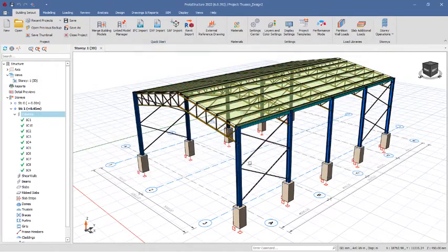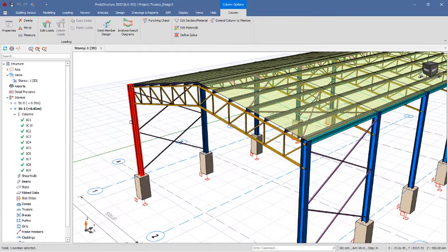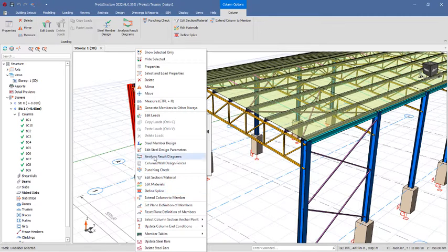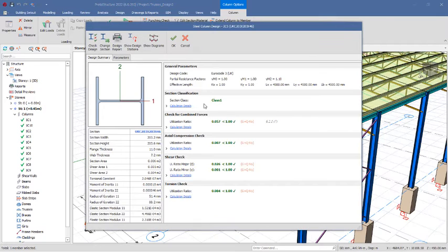Close this dialog. We want to be checking the steel stanchion to see if it is actually designed. So you get it selected. Alright, you right click and then click on the steel member design right there. This will open up a dialog that we will be able to use to check and confirm that the steel stanchion has passed design, as you can see, and the U ratio you can see is very far from 1. That simply means you can reduce the sections of this steel stanchion successfully, and it will still be able to carry the structure. So click on the OK option.